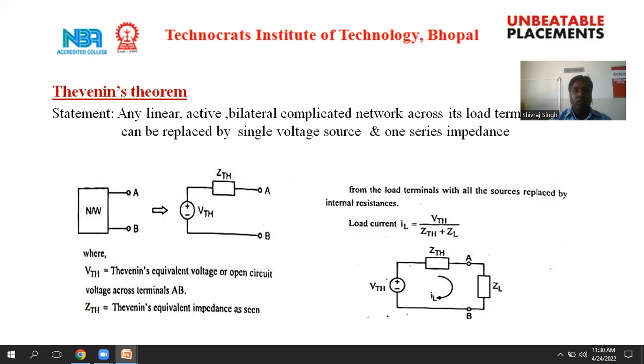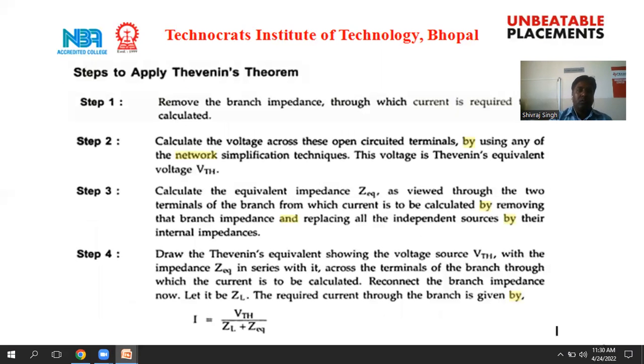So here we follow these steps to calculate the response. Firstly, we remove the load terminal. Then, in the second step, we calculate the VTH across the load terminal. For this, we remove the load terminal and measure the VTH in the open circuit.